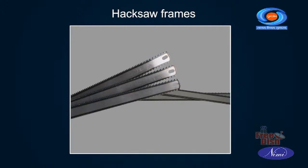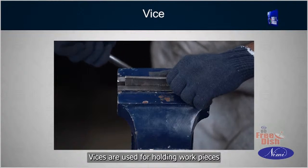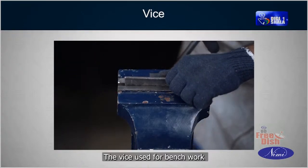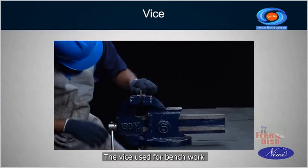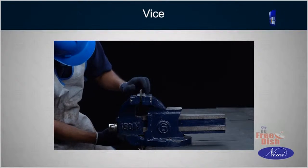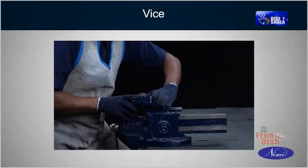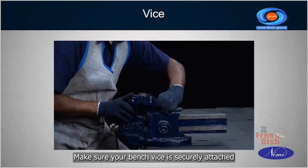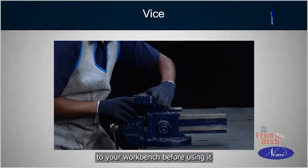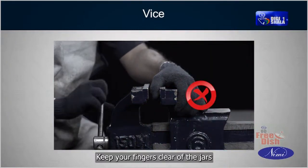While selecting blades, make sure at least 2 teeth of the blades will be in contact with the work at all times. Vices are used for holding workpieces. They are available in different types. The vise used for bench work is the bench vise or called engineer's vise. Before using the bench vise, make sure your bench vise is securely attached to your workbench before using it. Keep your fingers clear of the jaws.